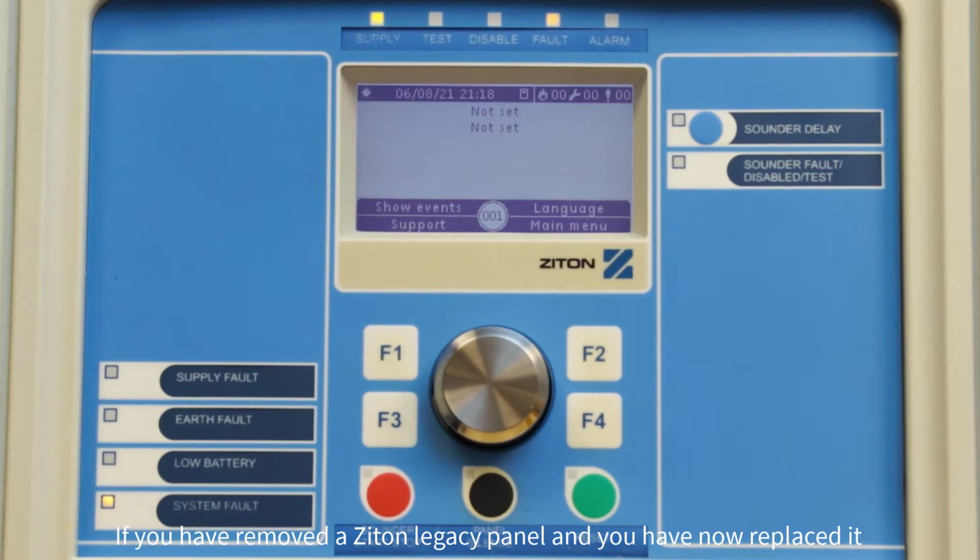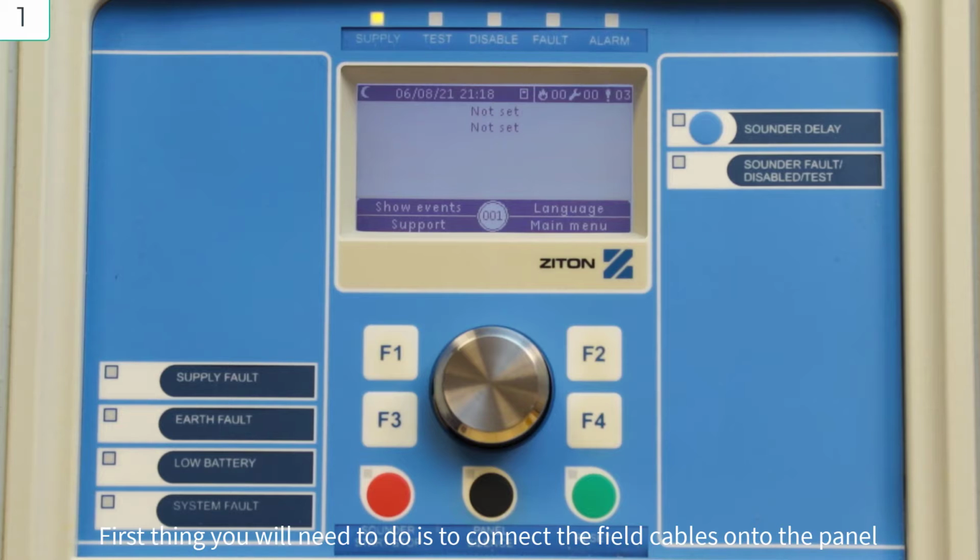If you have removed a ZP2 legacy panel and you have now replaced it with a ZP2 panel, this demonstration will guide you through the steps to get your new panel up and running. There are 3 tasks that need to be completed. First, you will need to connect the field cables onto the panel and connect the resistors to any supervised inputs and outputs that are not used.